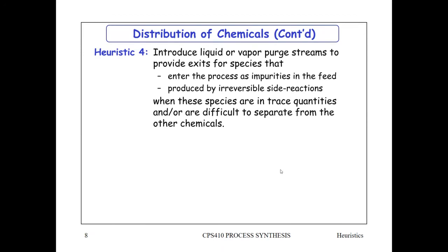And by using a purge, the reactor is using up your hydrogen and your carbon monoxide and increasing the concentration of the argon. So when you have your purge, you are losing some CO and hydrogen, but the recycle stream has increased the concentration of the argon because the other two components, CO and hydrogen, have been used up.